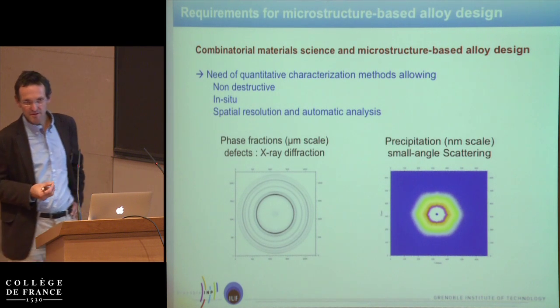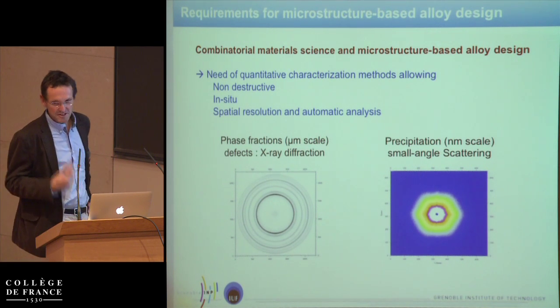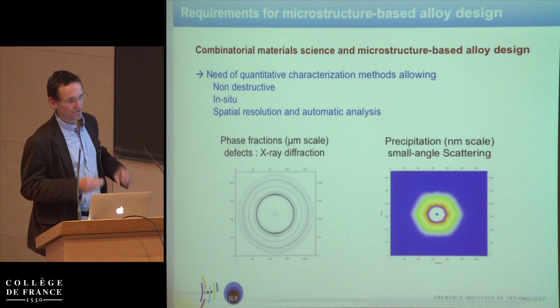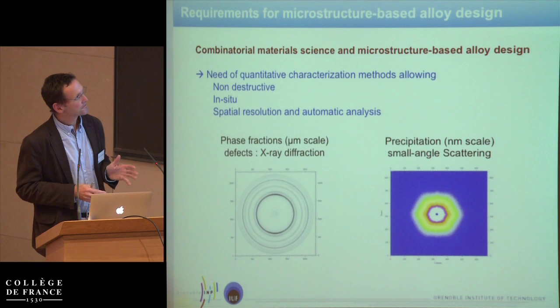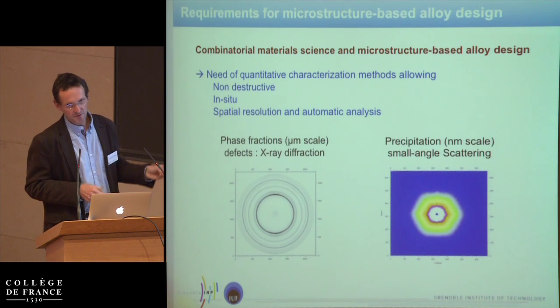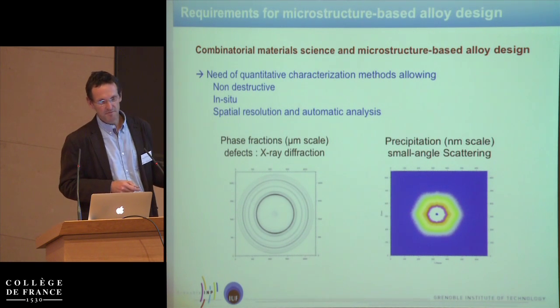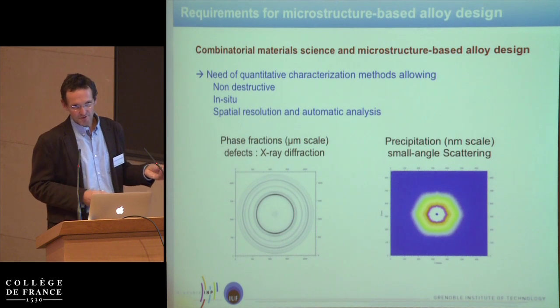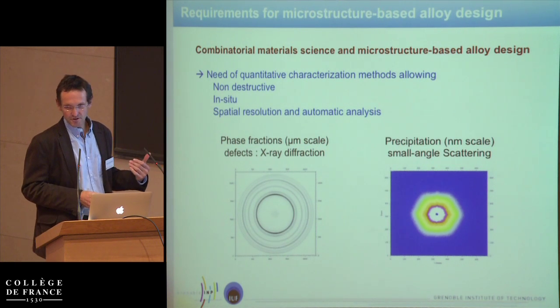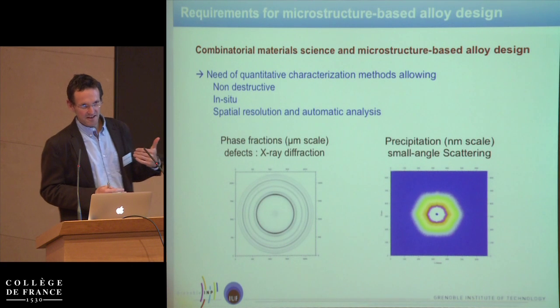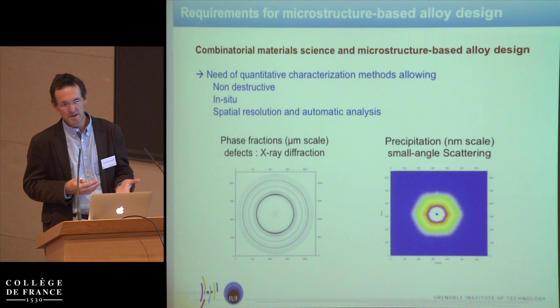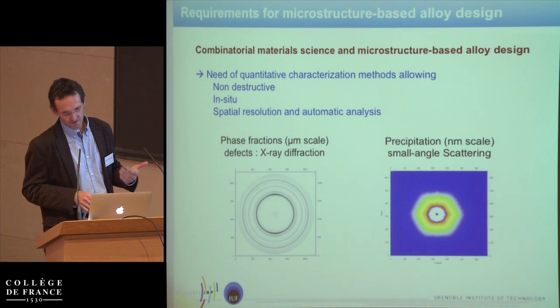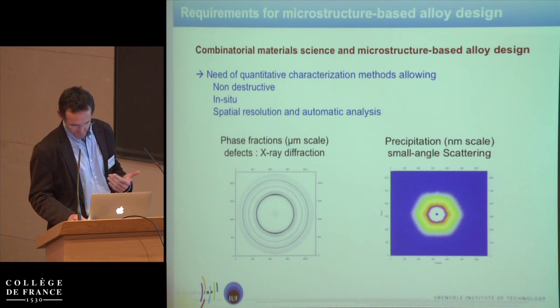And probably the X-ray methods are particularly well suited to that, because the size of the beam is of the micrometer to millimeter size scale, but the size of objects you're probing with these kinds of methods are nanometer size. So it's particularly suited to study the microstructure at the nanometer scale, varying in space at the micrometer to millimeter scale. And it's non-destructive and possible for in situ.